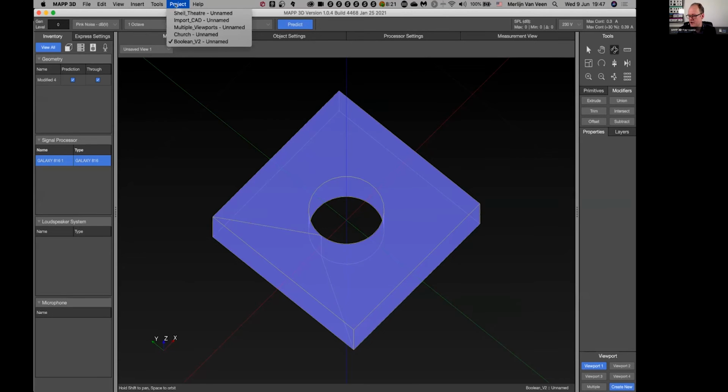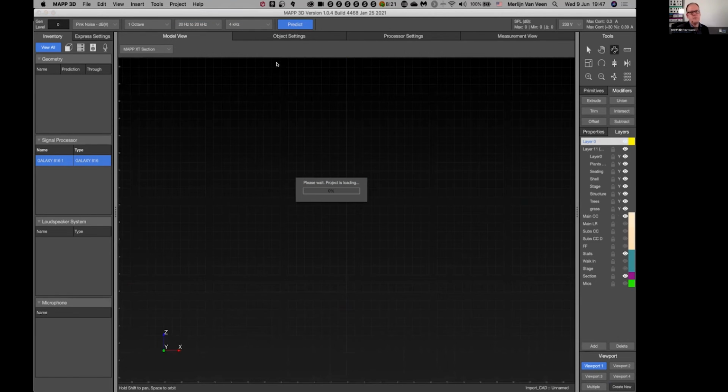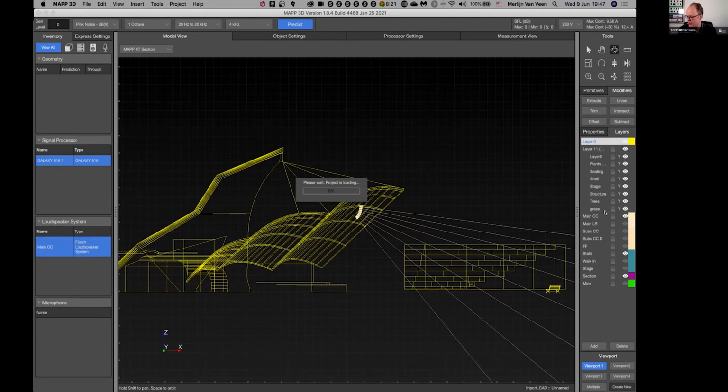Let's see if I have another one. Let's use this guy, because there's also the snapping tool, which I wanted to discuss. So notice that the imported DXF file over here has more structure. Layers are in there. It's already been layered in AutoCAD, and that allows us to remove some of the elements that do not serve our purpose at this point.